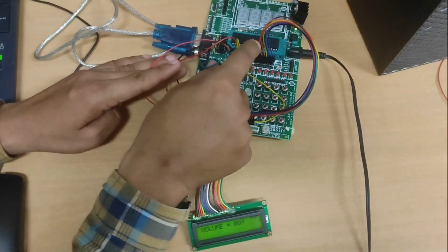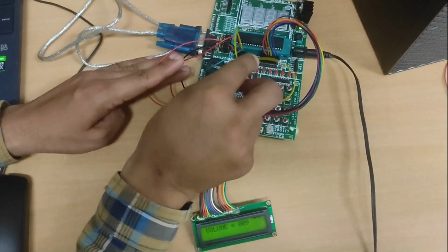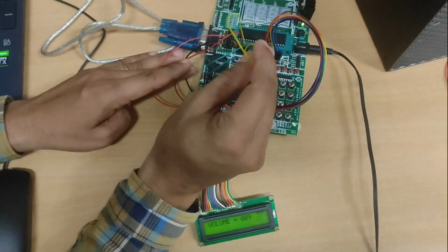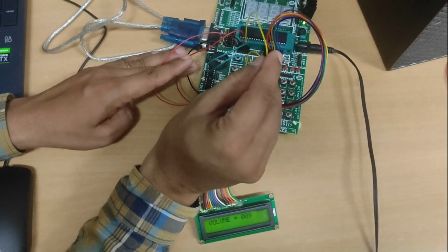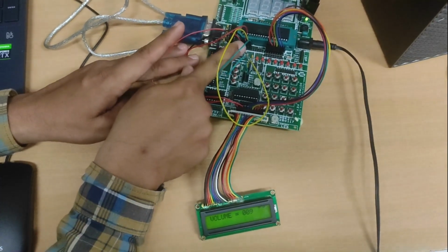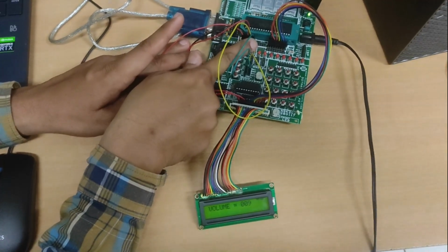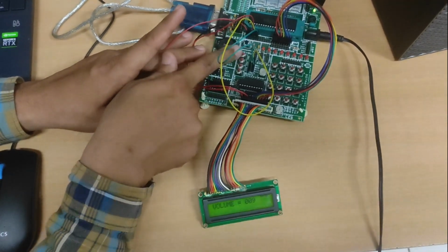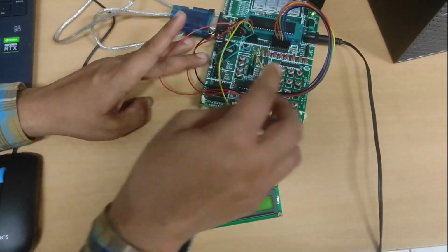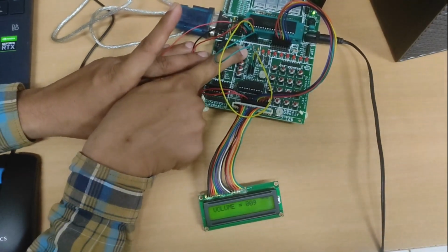And as usual, there are two switches. The volume up switch is connected to P2.3 and the volume down switch is connected to P2.4. Because 2.0, 2.1, 2.2 are for the LCD, 2.3 and 2.4 are for volume up and volume down. So these are the interfacing connections: two input GPIO lines and 11 output GPIO lines to interface the LCD, which helps us to increment or decrement